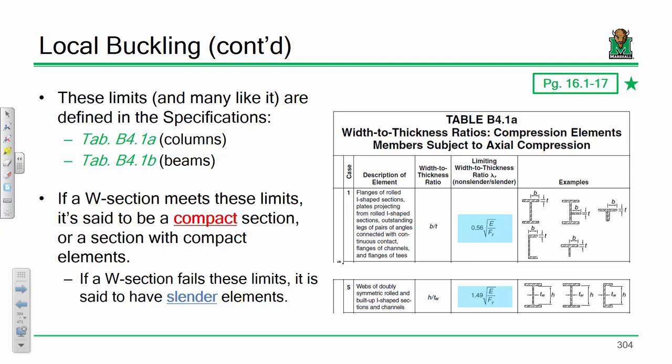That's a great question. So the question was, what's the difference between a built-up I shape or a rolled I shape? The difference is, you might hear me use the term plate girder versus a rolled beam. That's basically the difference. Rolled beams are the W shapes that come out of the manual. We take a steel product and roll an I shape. A built-up shape is when you're taking plate, plate, and plate and welding and creating a custom I shape. That's what we mean by built up.